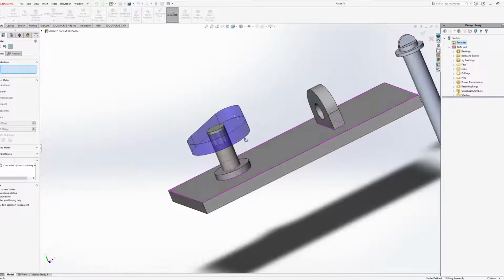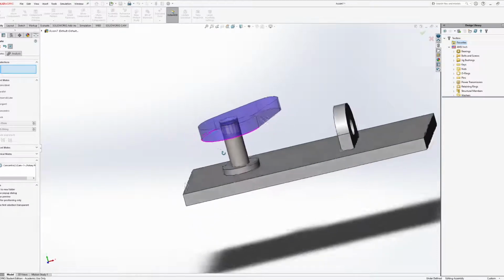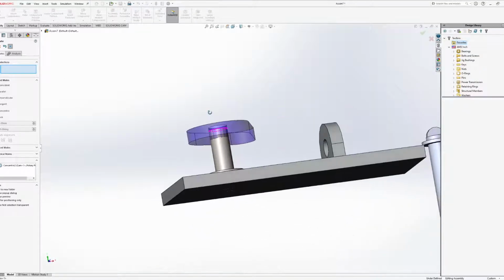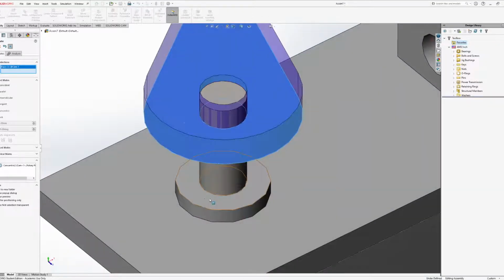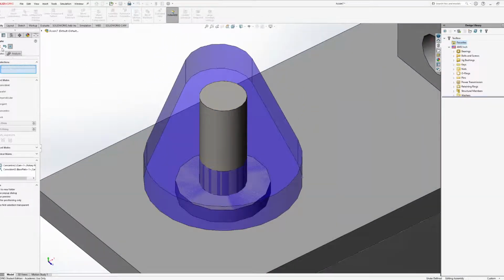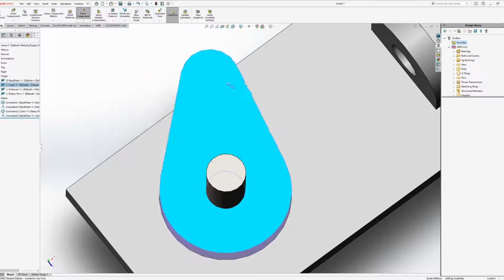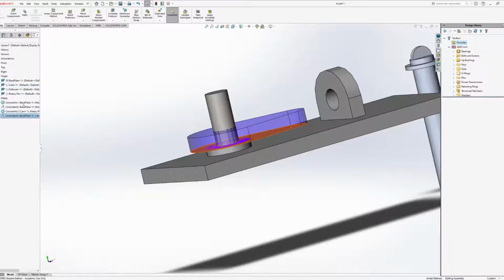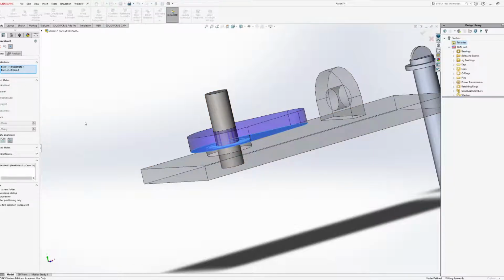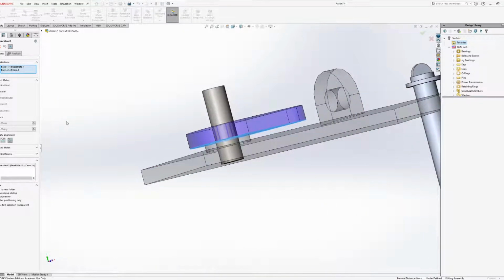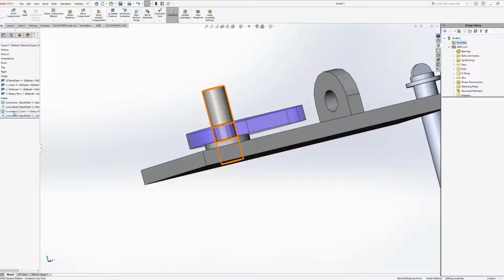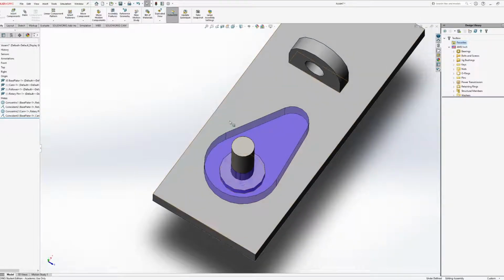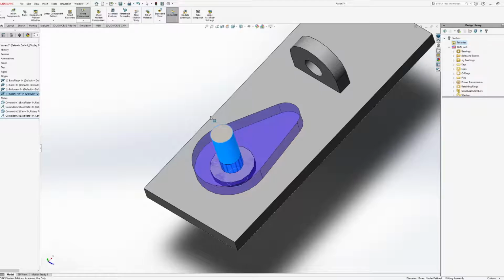And unfortunately, it can even go through this. So this is where I would probably use something other than a coincident, because if you watch this, if I hit this, and I hit that, if I confirm that mate, okay, it will actually move. Sometimes it doesn't move as proper as it should. And on top of that, occasionally coincident kind of deems it almost to be like they're glued together. But you'll see here, if I rotate this, it doesn't actually rotate the cam, which I want it to do.